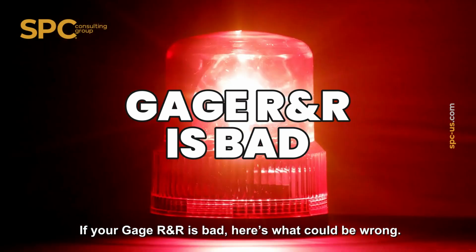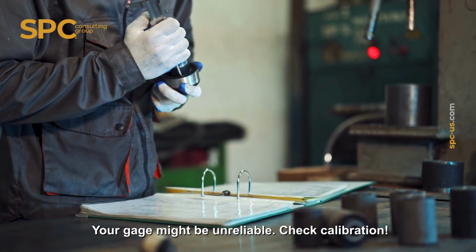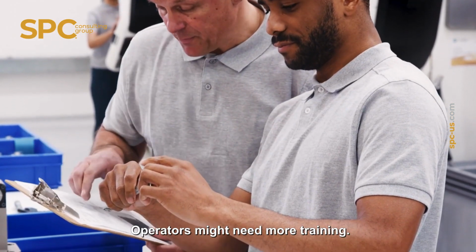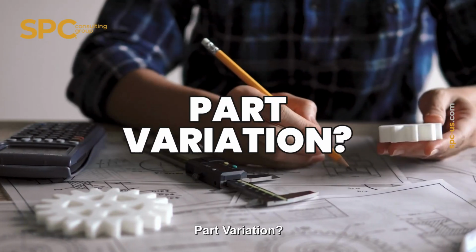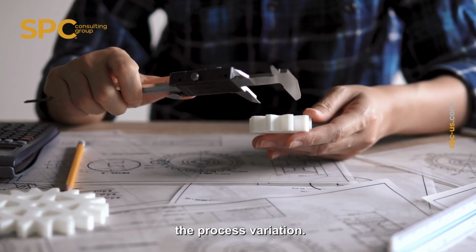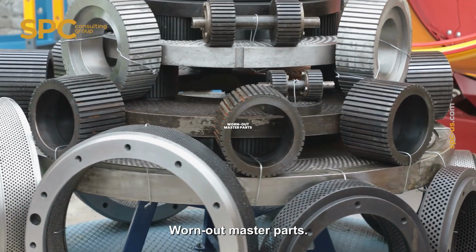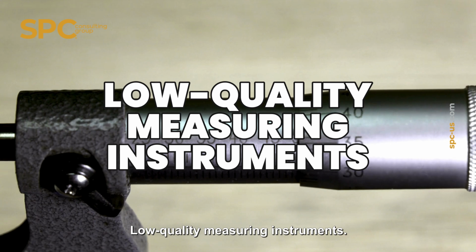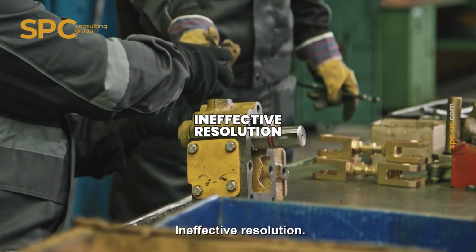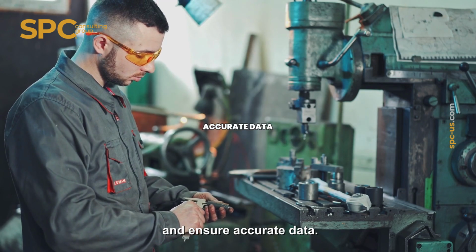If your Gage R&R is bad, here's what could be wrong. Poor repeatability? Your gauge might be unreliable. Check calibration. Poor reproducibility? Operators might need more training. Part variation? Make sure your sample set truly represents the process variation. Some common measurement system analysis issues include inadequate calibration, worn-out master parts, low-quality measuring instruments, application errors, ineffective resolution. Fixing these issues and redoing the study will help improve your measurement system and ensure accurate data.